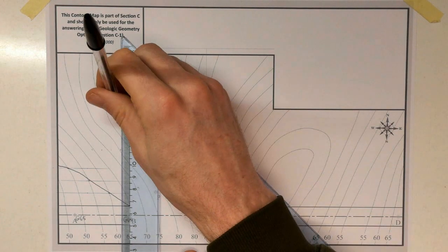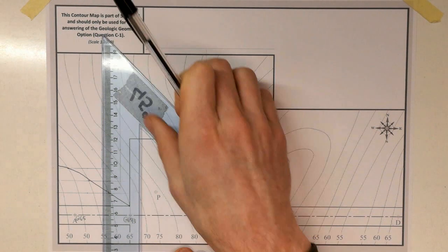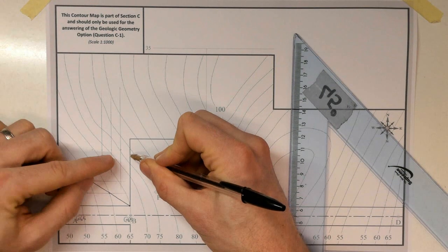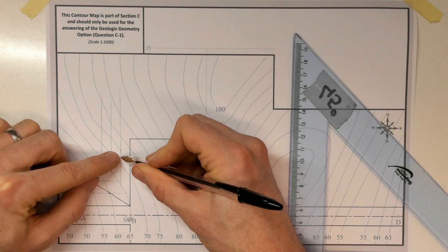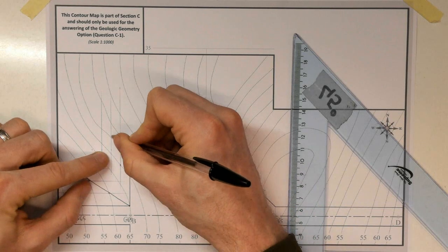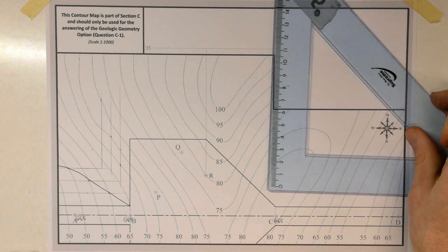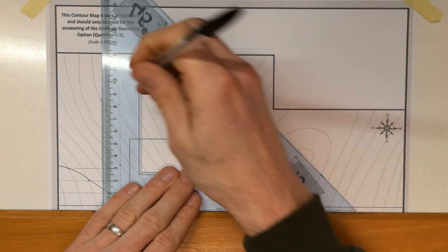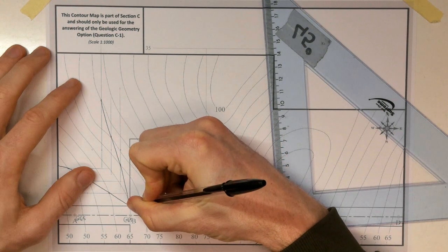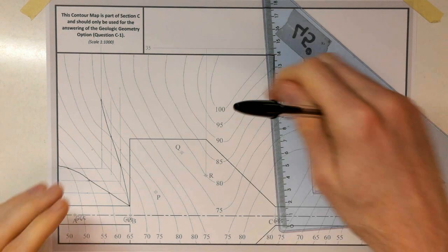So draw my contours, or draw my intervals. I'm at 65 at road level, then I'm going up because I'm cutting in. So here I'm going to be at 70, so 70 is there, then up to 75, 80, and extend around, then I won't intersect. Just extend it on there, so that it doesn't intersect, so I just have this line here, and start my fill. Probably would have created another point away up there, but we'll be finding another intersecting line coming across.